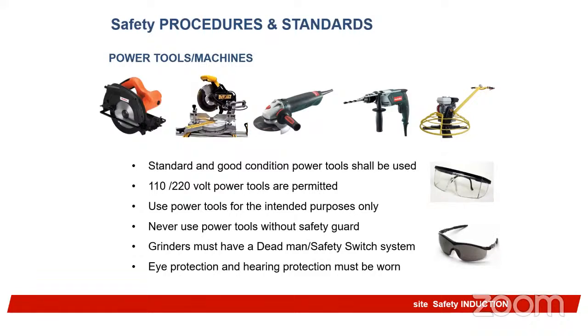Use power tools for the intended purpose only, for the purpose they have been designed for. Never use power tools without safety guards. Grinders must have a dead man switch system. Then eye protection and hearing protection must be worn.